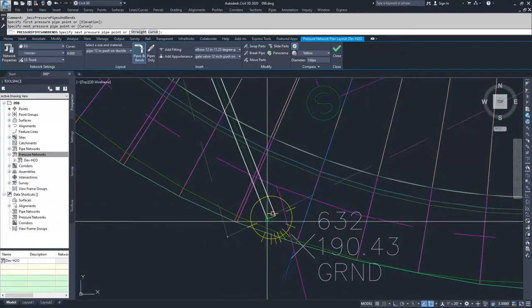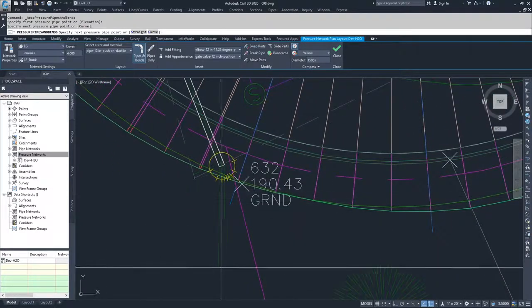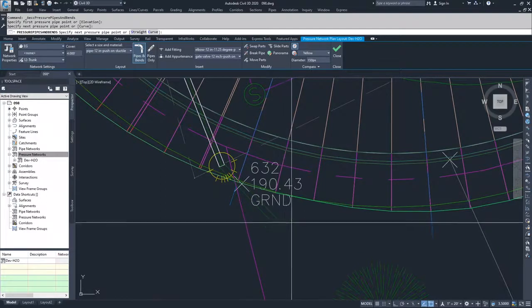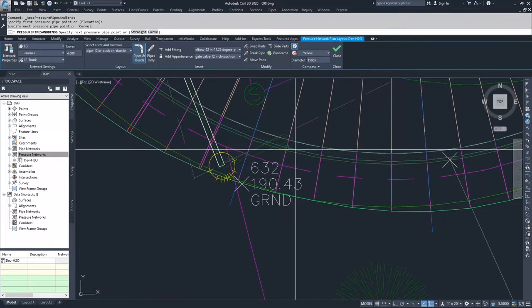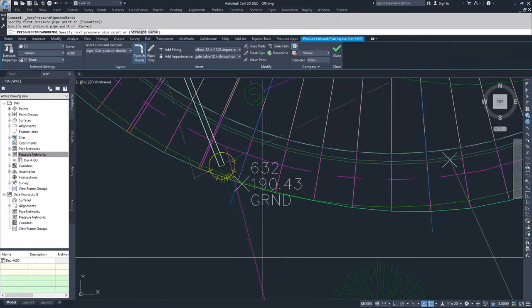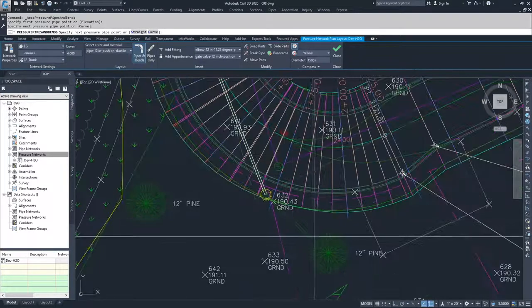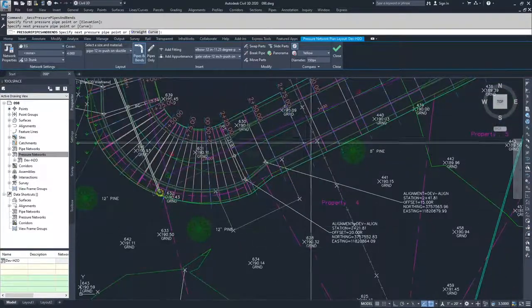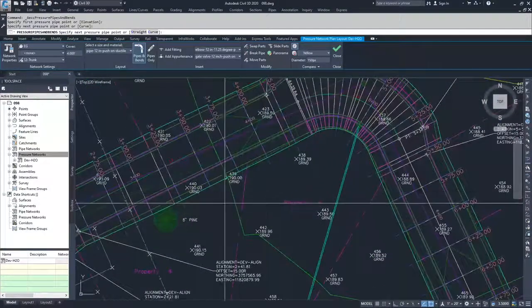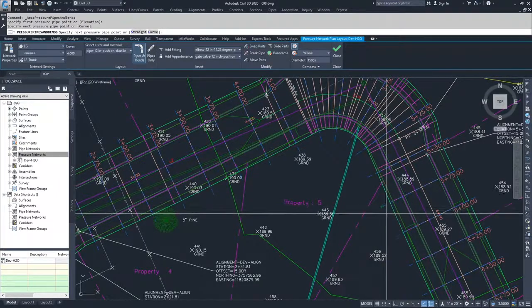And so now what you get to see is the compass. The compass is a circle with tick marks at the locations of the bends that we have in our parts list. So we have our 90, our 45, our 22.5, and our 11, and our 0. From these, you can lay out your pipes. Since I set this up to be a 90, I'm going to go with a 90 here. I'm going to shoot down to this end down here, and then I am going to click in.